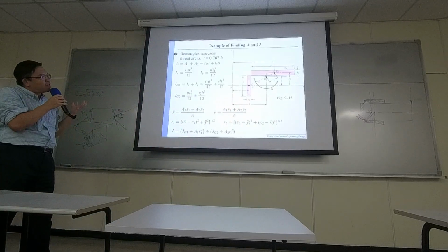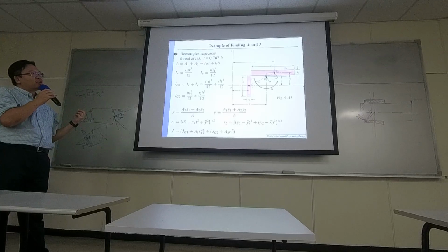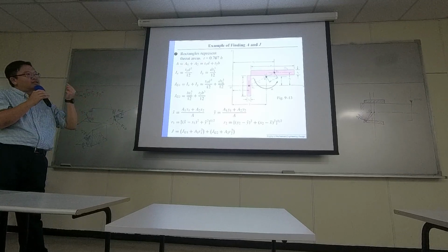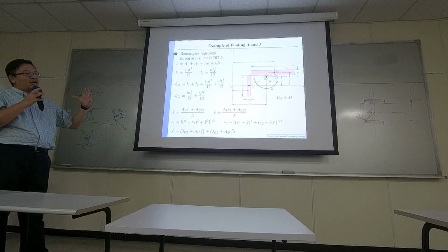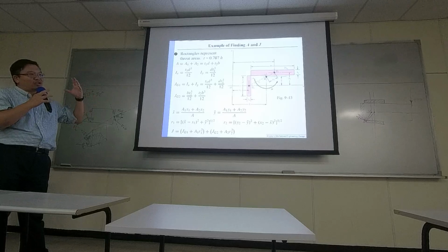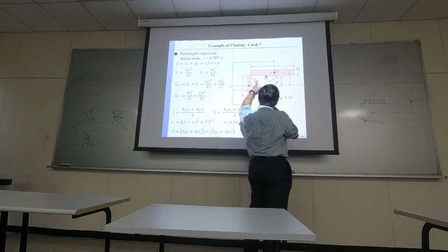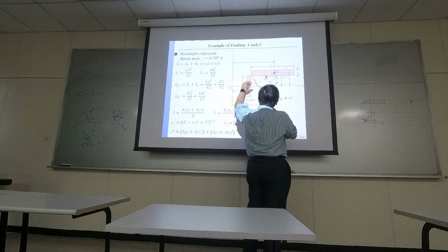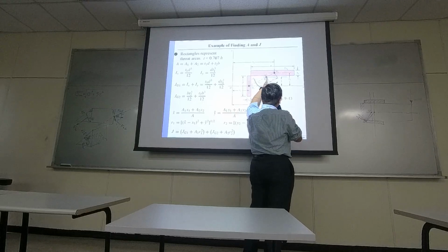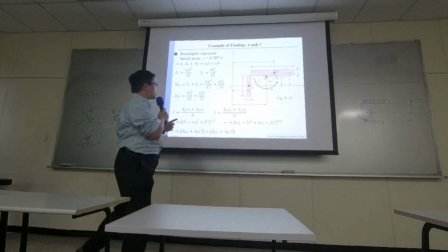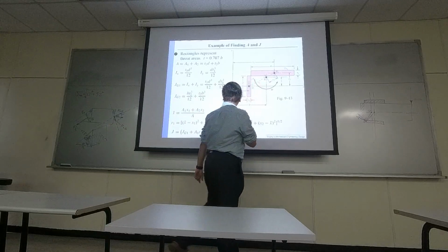You can treat them as materials with the same density, but the area represents their weight. When the area is larger, it's like the volume is larger, so it's heavier. It's like you are trying to find where is the balance, where is the center. So these two masses will balance for a particular G. That's how you can compute the position of the overall center.